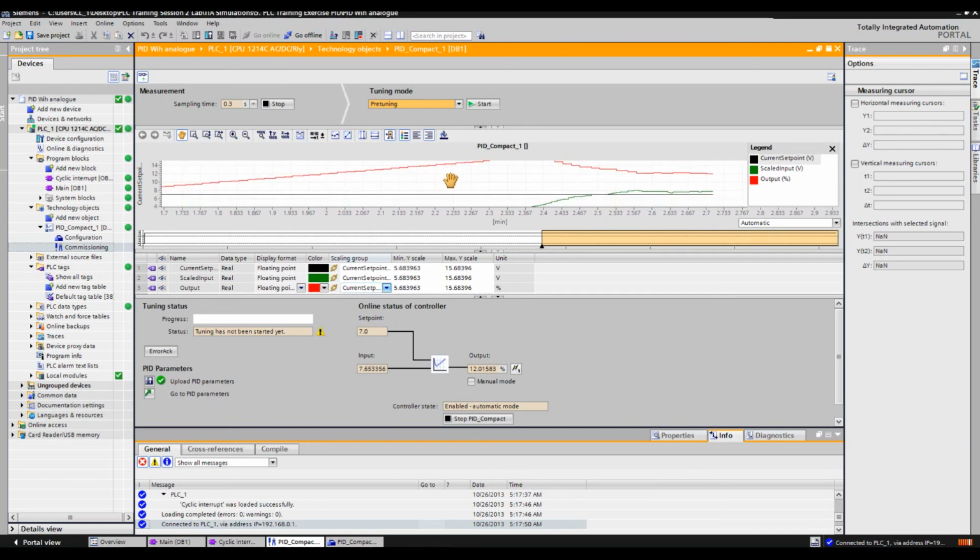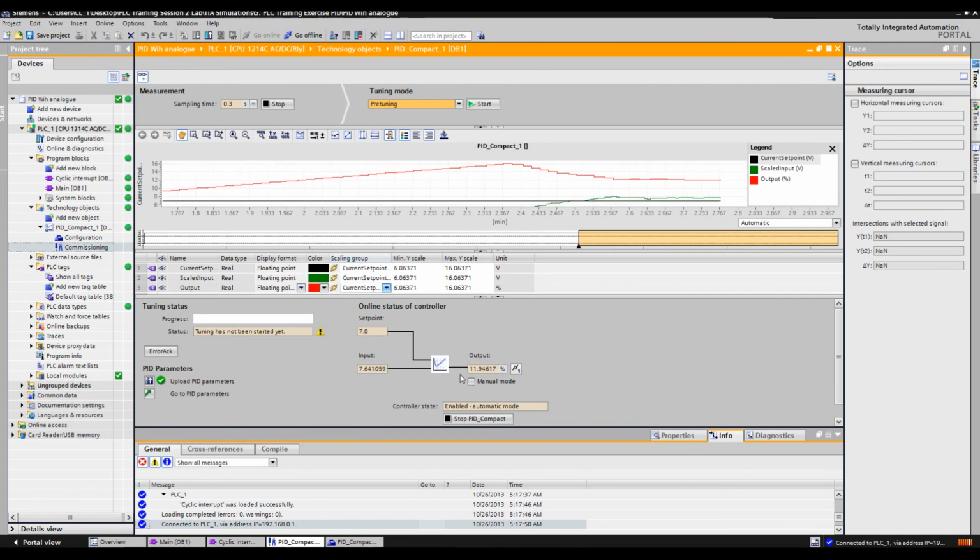So this is the dynamic behavior of a PID controller, that we have a set point and a PV and the output action. Now this output action can be altered with the gains: proportional gain, integral gain, and derivative gain. You can make the controller aggressive or less aggressive, P controller, PI controller, PID controller, depending upon your application. So this is a simple demonstration of how a PID controller works.